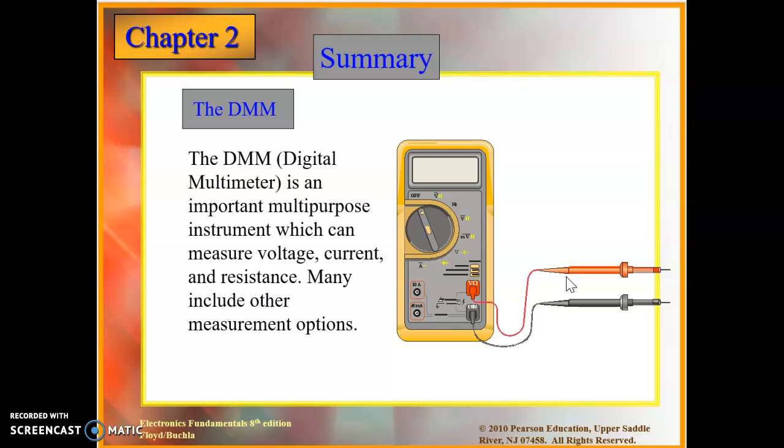If you're going to measure current, then the multimeter turns into a zero resistance, so when you place it in the location you want to measure, it reads only the current that goes through it, and it doesn't affect the behavior of the circuit.